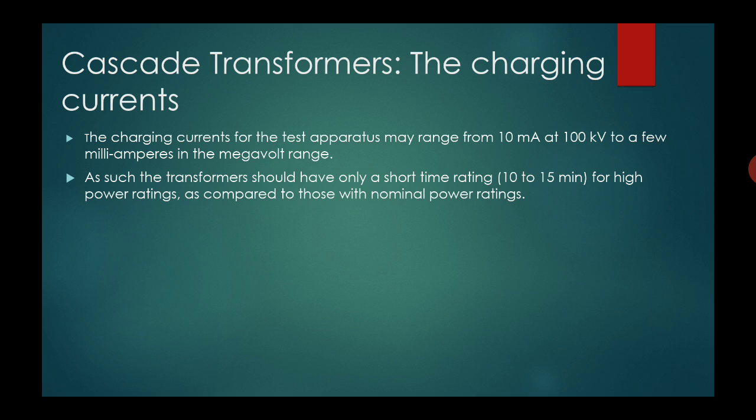So when we are doing this testing, the testing should not be more than 10 to 15 minutes, because the high voltage that is being provided here cannot be used for a long period of time. So it is only for a small period of time, that should be kept in mind.